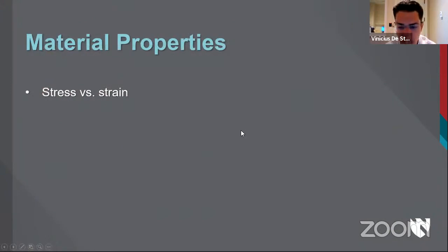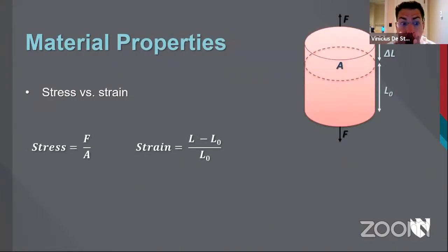And when we talk about biomechanics, the major concepts that you have to have in mind are those of stress and strain. So what is stress and what is strain? Again, bear with me here, okay? Stress is, whenever you take a tissue, a solid, whatever you're using as your object of study, the force that you apply in a specific direction divided by the cross-section area of that object.